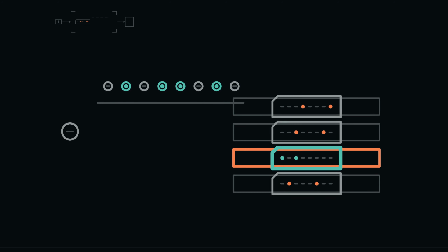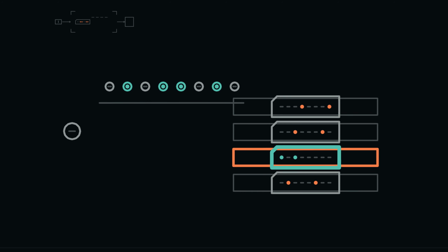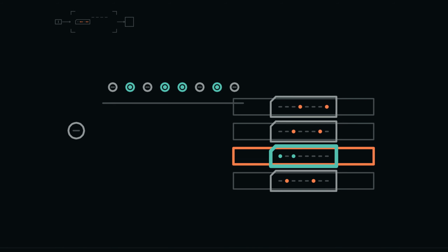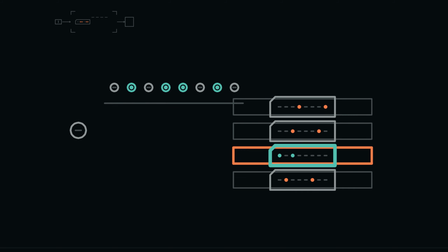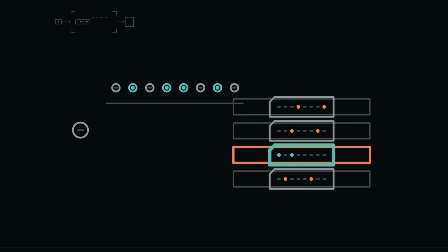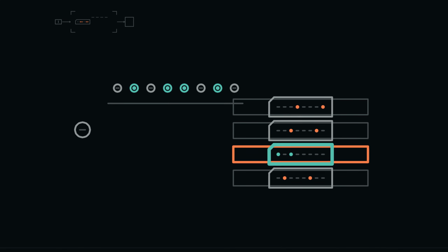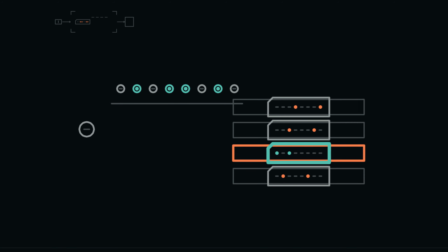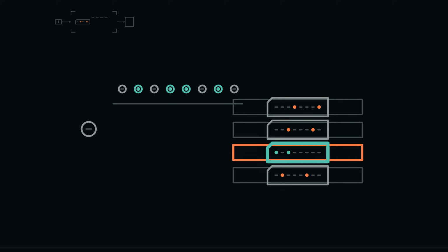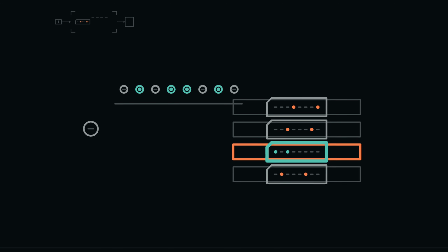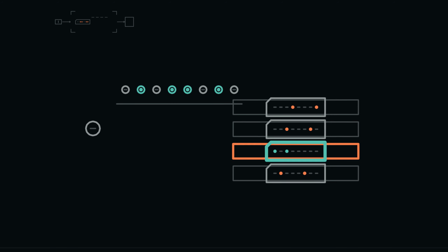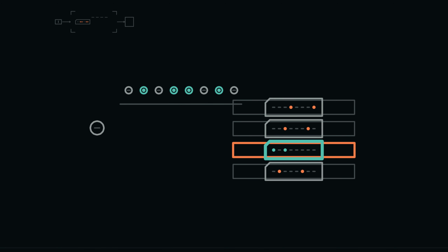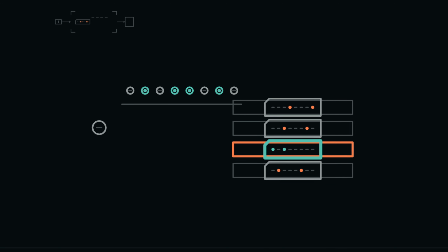Test the invariant on 4 rows. Row 1 contains hexadecimal 11. Row 2 contains hexadecimal 22. Row 3 contains hexadecimal 33. And row 4 contains hexadecimal 44. The address selects row 3, the data input presents hexadecimal A0, and write permission is active. Before the edge, all old values remain. After the edge, row 3 contains hexadecimal A0. Rows 1, 2, and 4 retain 11, 22, and 44.